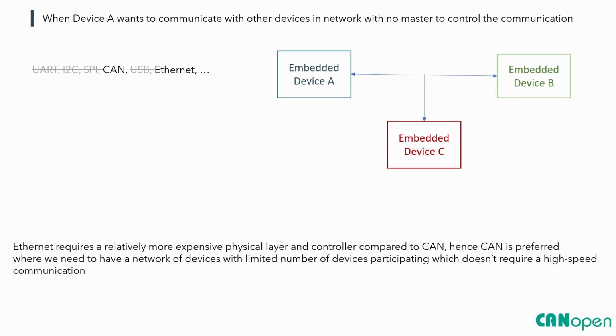For example, let's say you have a console, or in a car example, you have many sensor nodes and you basically want to collect some information from these sensors, and some ECU or central units just need to get that information or transmit some information, or there are some sensor nodes that just transmit some information. So you see in these cases it's a very simple communication. We don't need very complicated network scenarios. So in these cases, CAN would probably be a better choice compared to Ethernet.